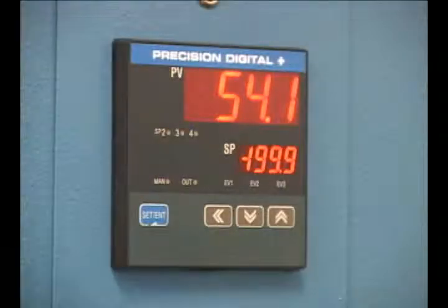The last setup requirement, now that my outputs are programmed to be alarms and PID outputs, and that my input has been programmed to be an RTD, is to auto-tune the system for this particular setup. Auto-tuning PID controllers means you don't need to know what your proportional, integral, or derivative values are. It'll run the process up and down, acquiring what those PID values are for you, and then eventually return to normal operation based on the set point.